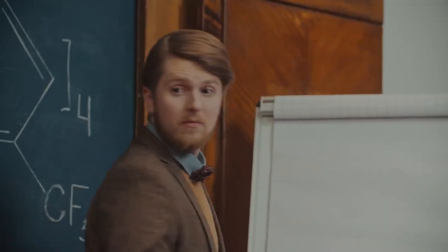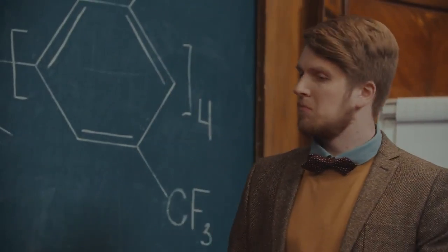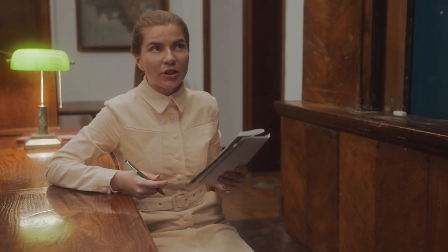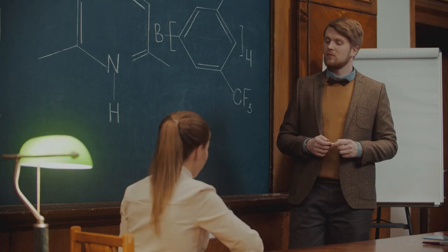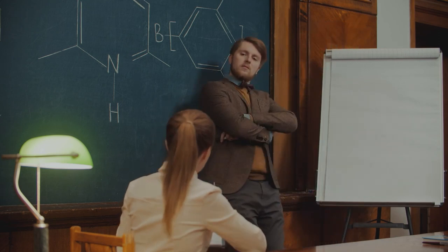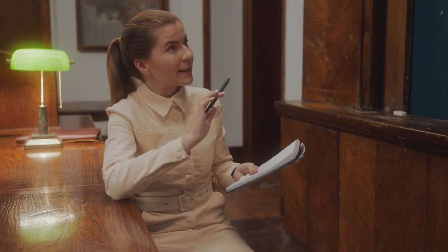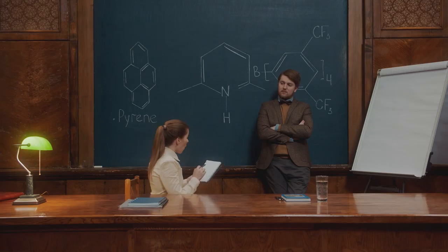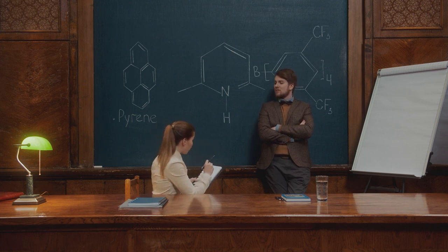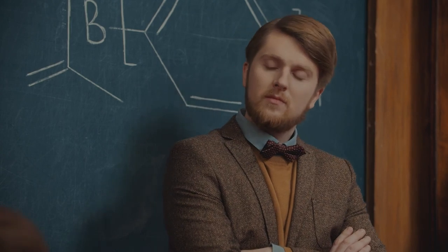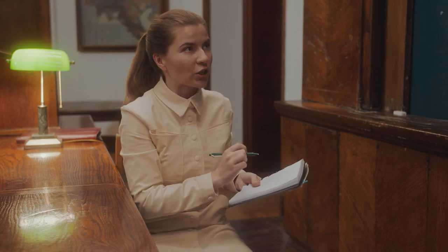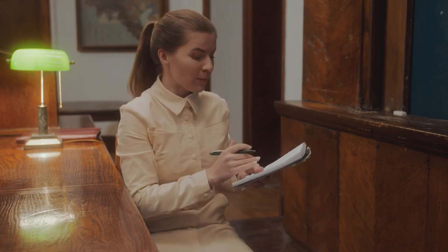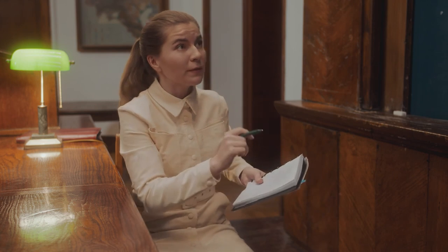I have the answer, Professor. The questions are not that difficult. Go ahead, Miss Doolittle. The answer to the first question is the following. The smallest sorption surface belongs to the surface flow wetlands because the sorbents are represented by stems and roots of the wetland vegetation, although the specific surface area of the vegetation is far smaller than the total sorption surface in the substrate, which is used in the subsurface flow wetlands. Now the answer to the second question. There is direct mathematical relationship between the specific sorption surface of any treatment facilities and its water treatment efficiency.